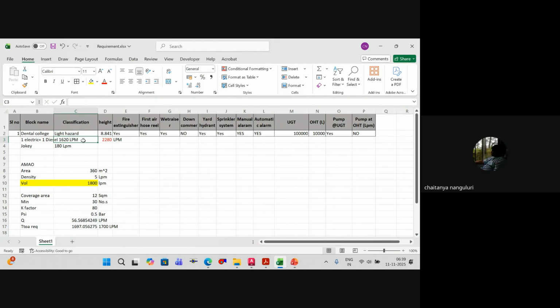Now, once the firefighters have come into the picture, and let's say you have sprinklers as well as hydrants running, don't you think your water will be there only for a lesser time? Firefighters are also risking their lives and others' if they still allow sprinklers. Manually you can throw the water exactly where the fire is. So in that case, if the diesel supply is there, we use the hydrant system only, not the sprinkler system.